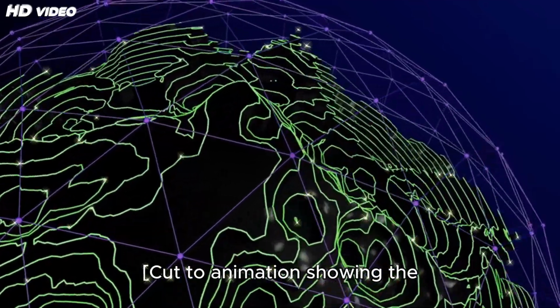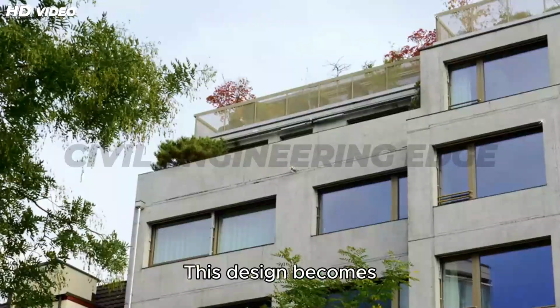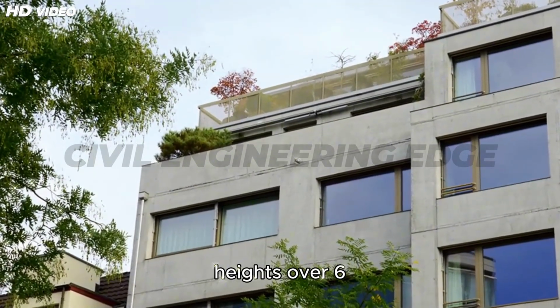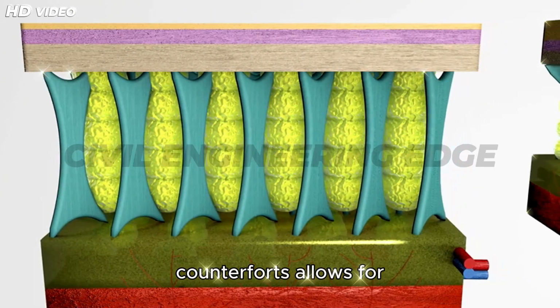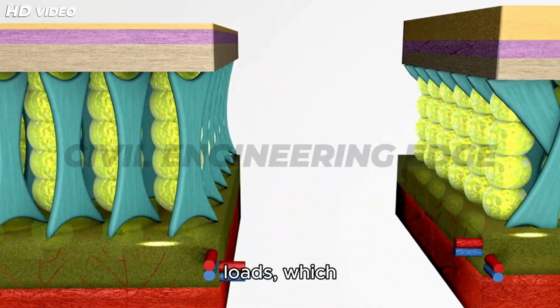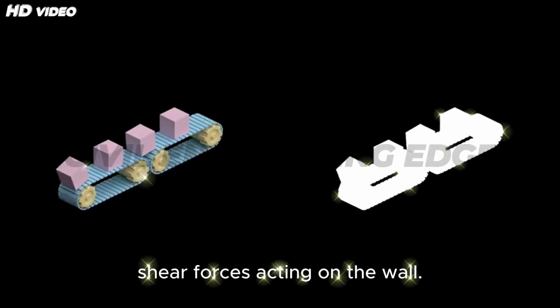Cut to animation showing the structural load path and earth pressure distribution. This design becomes particularly beneficial for heights over 6 meters, where cantilever walls become uneconomical. The inclusion of counterforts allows for thinner stem sections and more distributed loads, which significantly reduce the internal moments and shear forces acting on the wall.